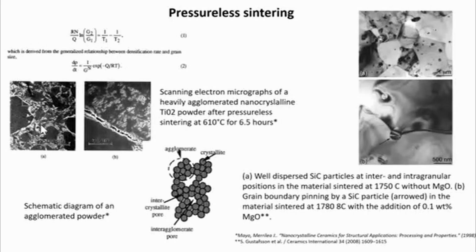As the authors showed, the silicon carbide particles were well dispersed in the microstructure and located predominantly in the interiors of the aluminum oxide matrix grains. Pinning of grain boundaries by the second phase in the matrix material of nanocomposites could essentially suppress grain growth. These effects could be used for microstructure engineering of composite materials.